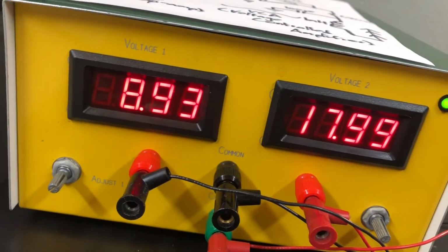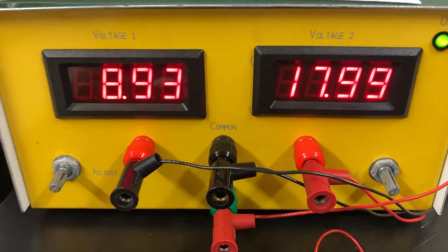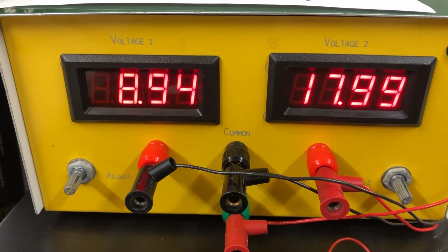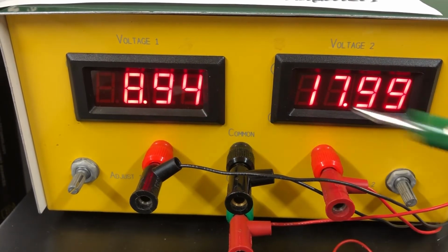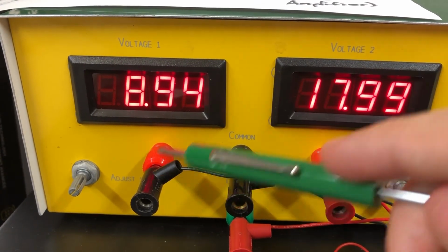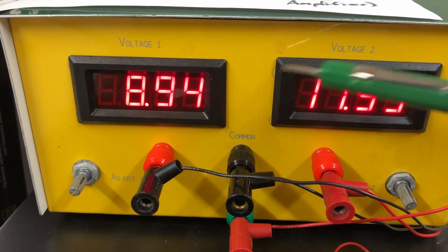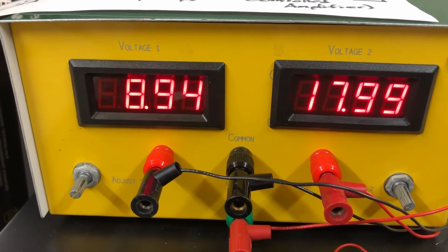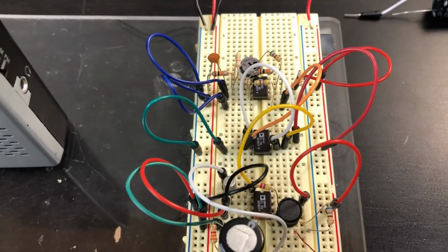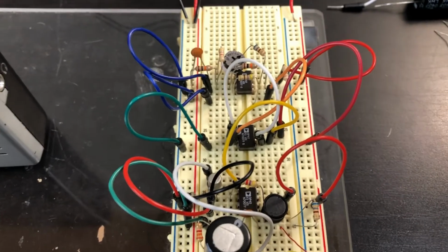Something I didn't mention earlier is the power supply for this. You're supposed to be using positive and negative 9 volts. Since I don't have a negative voltage supply, I just use 9 volts as my ground, and it achieves the same effect with this ground being 9 volts under and then this supply being 9 volts over. In reality, you could use 2 9-volt batteries, but I wasn't planning on this being super permanent, and I don't even have 2 9-volt batteries.